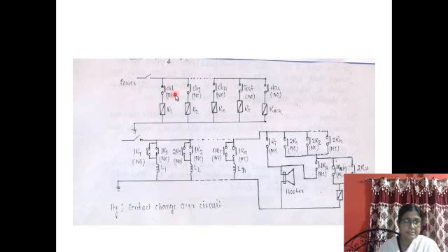I think it is clear to you that whenever this channel is in healthy condition, this being normally closed type, this contact is in closed condition. So this path will provide the power to the device. So relay R1 is in energized state.